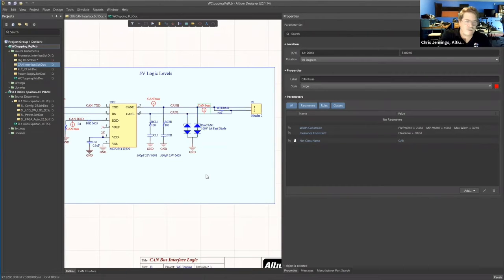I think it was roughly 20 designers to a layout engineer at that particular customer. So obviously the layout engineer doesn't know all of the ins and outs of each of the designs, but when they get something like this, where they actually have a rule that says, hey, this is called a high power class, and they put rules in there like clearance constraints. You need to have 400 mils of clearance or whatever the number was.